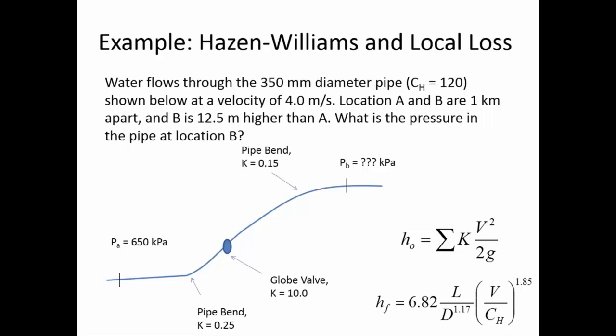What I hope you remember from the lab last semester is that laminar flow in a pipe is actually very rare. It's not very common that the water is moving slowly enough for conditions to be laminar. So 2.0 isn't going to happen very much when you're applying the energy equation.